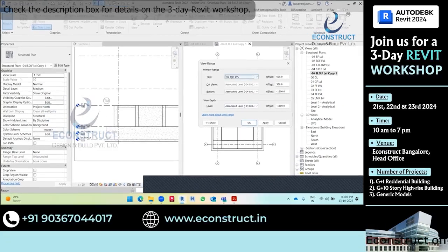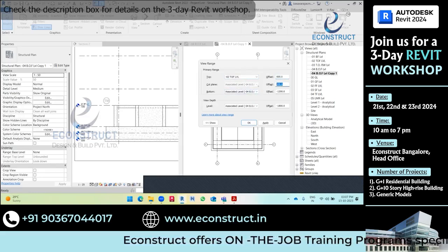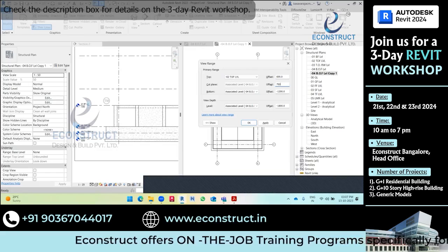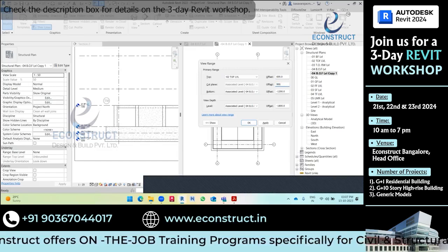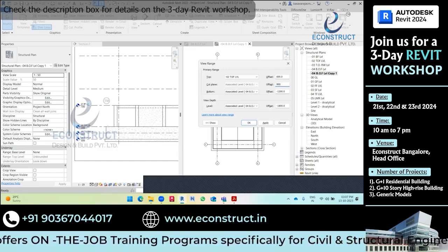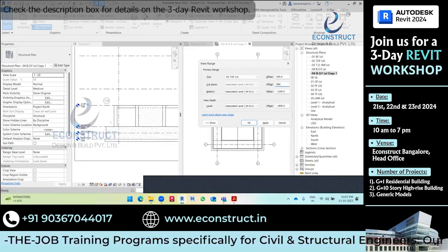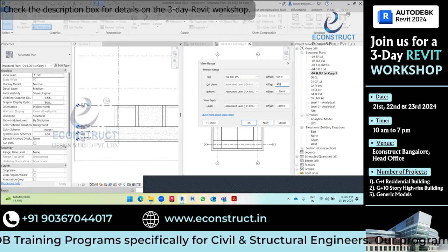Top level, what I will take from the top of the level, I will give some 600 offset. Okay, no problem. Cut plane, from this bottom of the footing level, I will take some 900 mm because the footing height is 800. I will shift 100 above. So 900.